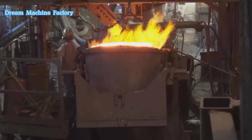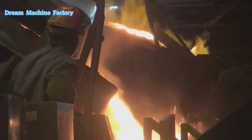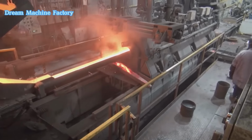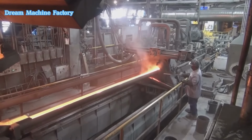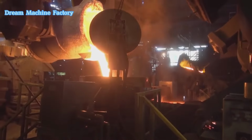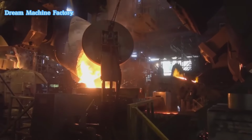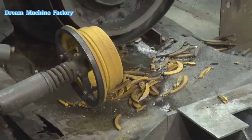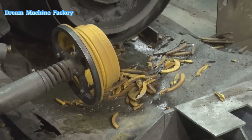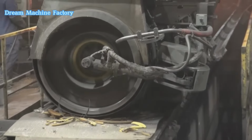Casting is the process where molten iron is shaped into ductile iron pipes using the Delavaud centrifugal casting method. This method ensures uniform thickness, strength, and durability while allowing for efficient large-scale production. The process begins when molten iron of the correct composition is transferred from the forehearth into a pouring ladle. This ladle holds enough molten iron to cast multiple pipes before needing a refill.